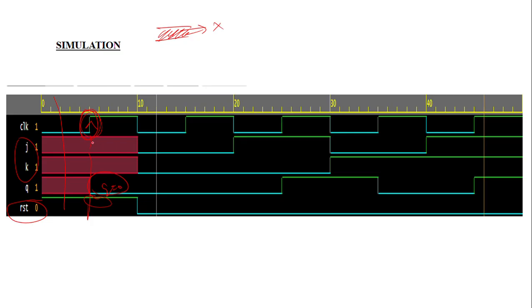Because of this, you have to understand why I made the test bench like this. You have to know this difference. Whenever there is a passage of clock, only then your flip-flop is going to be activated. Before that it takes unknown values.